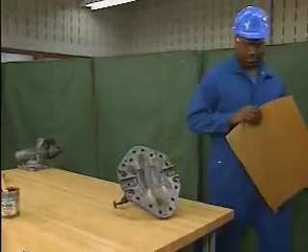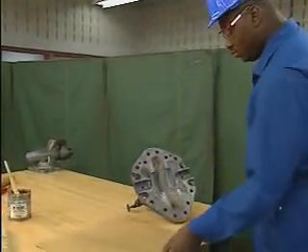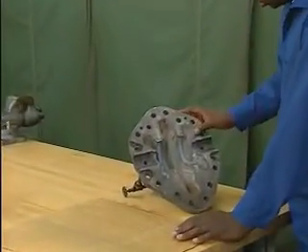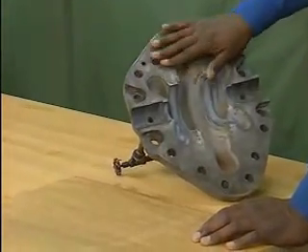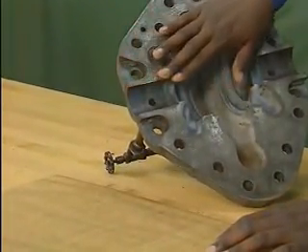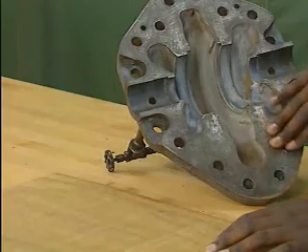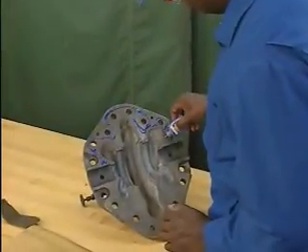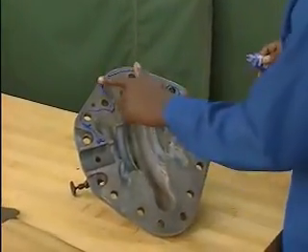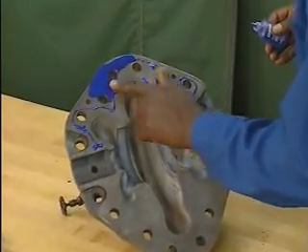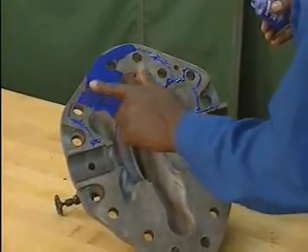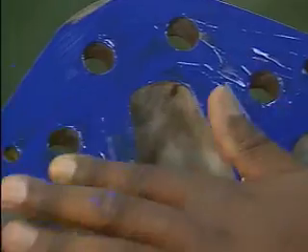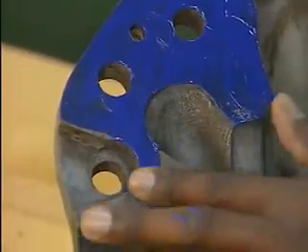After the mechanic obtains the correct gasket material, he must accurately cut a gasket to fit the shape of the sealing surfaces. In order to do this, he must transfer the shape of the sealing surfaces to the gasket material. This can be accomplished by coating one of the sealing surfaces with a substance that will transfer easily to the gasket material. In this example, the mechanic coats the sealing surface of the upper half of the pump casing with a type of dye called bluing.